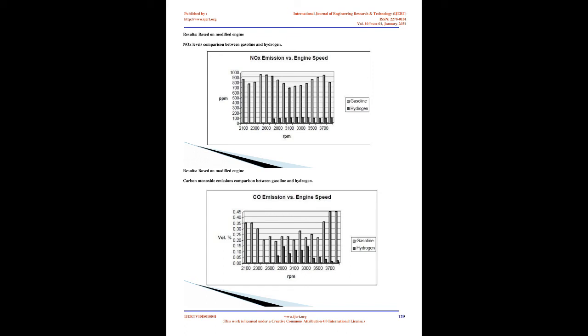Large reduction in cooling power. The water pump and fan outputs are reduced. Possibility to suppress the water cooler. Less inertia due to the lightness of the moving parts. Friction losses, theoretically higher in the 6-stroke engine, are balanced by a better distribution of pressure on the moving parts due to the work being spread over 2 strokes and the elimination of the direct combustion.